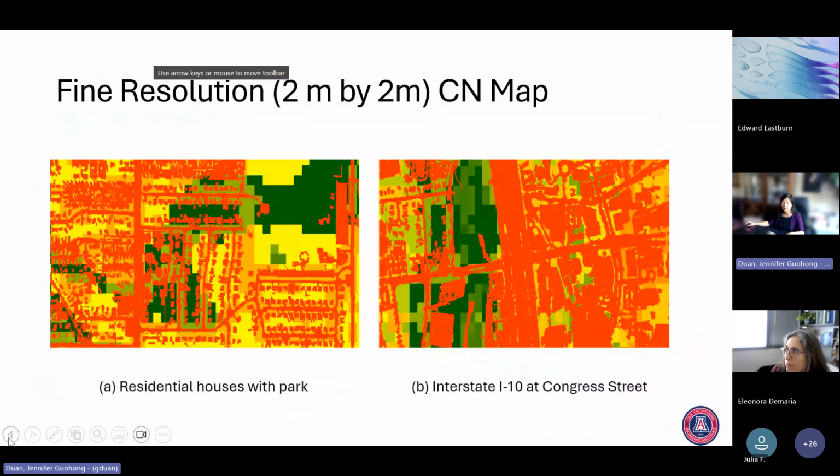Okay. So right now the runoff models like FLO-2D or HEC-RAS models, when they go into urban areas, have backyards. You have a well or you have a pond, and the water is ponding there, and then you can simulate those. The simulation cells can now be a meter by meter resolution. If there is ponding water, the curve number is going to be 100. I mean, that means that it is water in the pond.